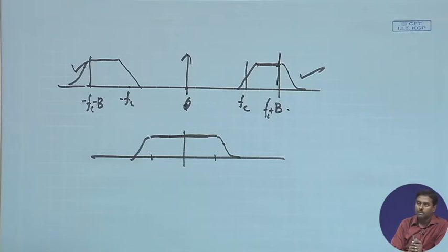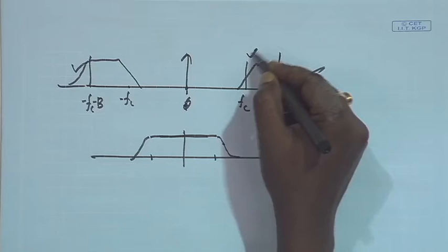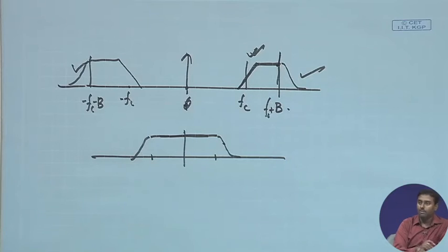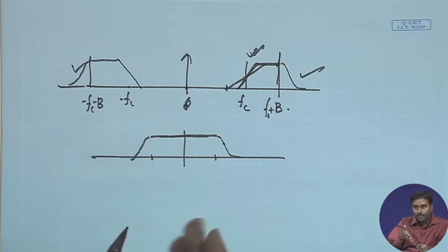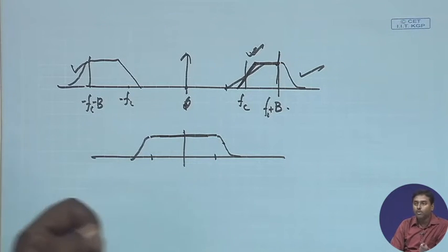So, that is how generally VSB signals are generated. All you have to do is employ this filter and characterize this roll off properly, whatever roll off you wish to do. Now, regarding the roll off, it depends on what kind of circuit you can choose, and accordingly there will be a trade off of how much bandwidth you take. Suppose you want a little lesser roll off, then the filter characterization will be simpler, because you do not need to go for a very higher order filter. So, it will take some extra band. If you start going towards higher and higher order filter, the roll off will be sharper and you will be saving more and more bandwidth.